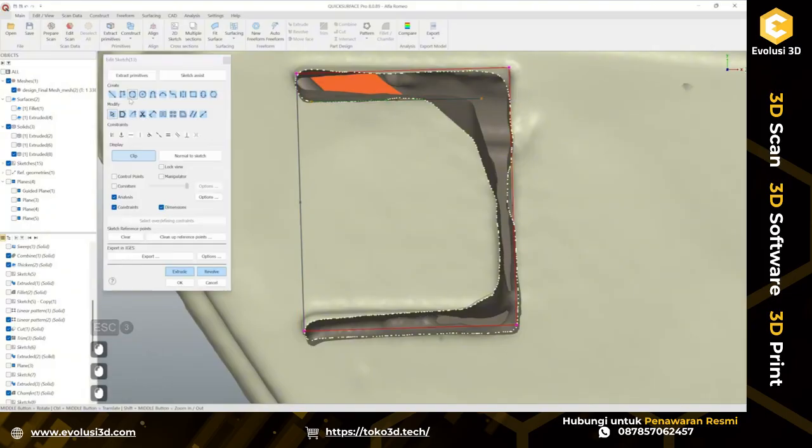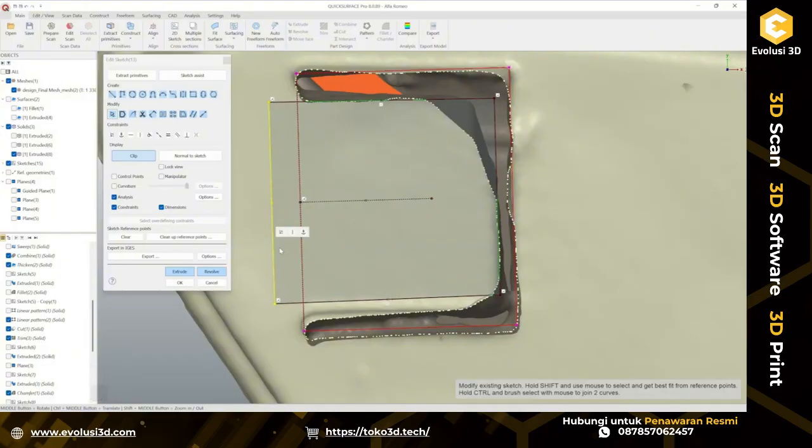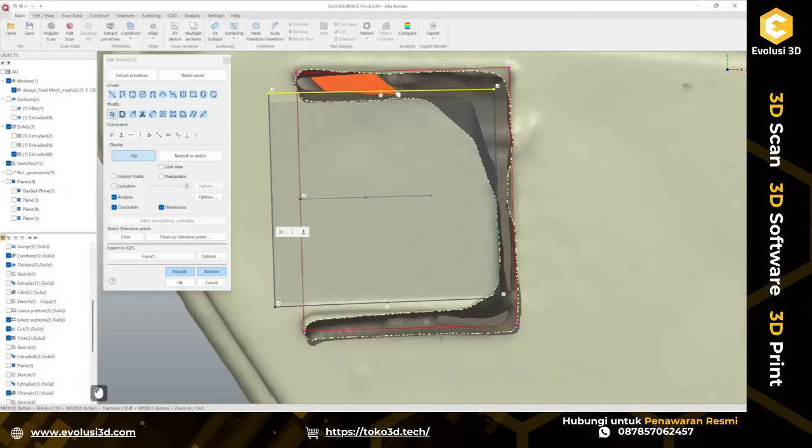Let's convert this edge to a line. Let's create construction geometry for mirroring. Select this line, construction line, mirror. Let's close one side. Let's close another side. So here we have some information to align it to. Good. Let's just extend it further on the front side. Of course, here we can see that one side is thicker than another side. And probably we want to move it slightly, but still it's quite complicated. This side, as we know, was broken.